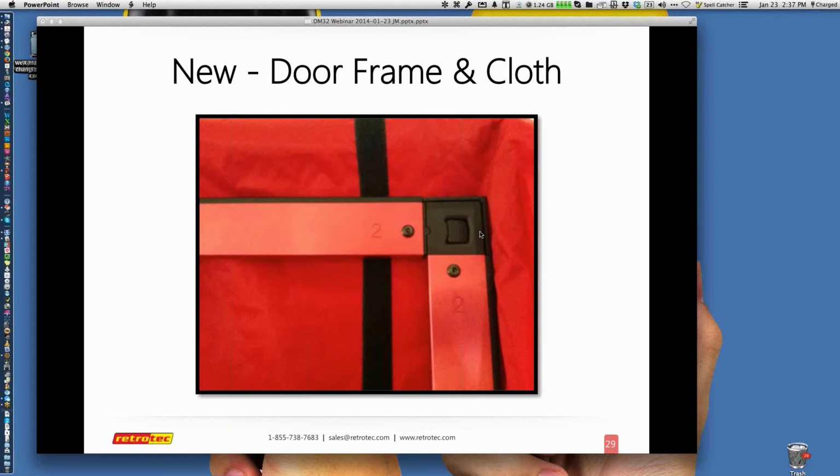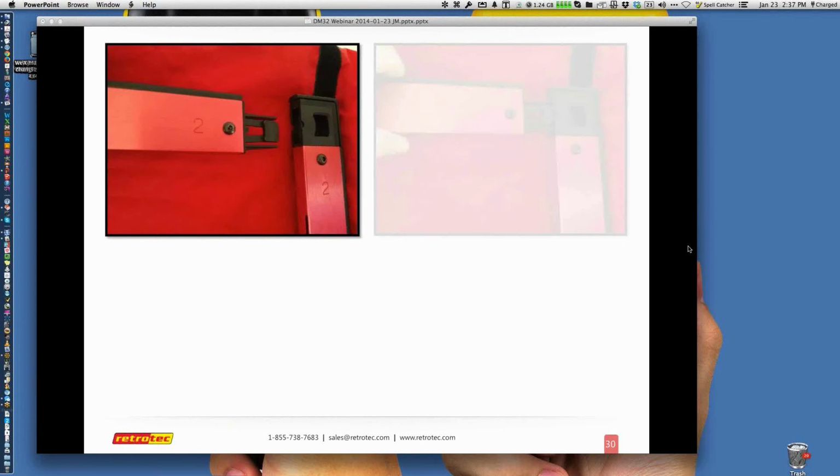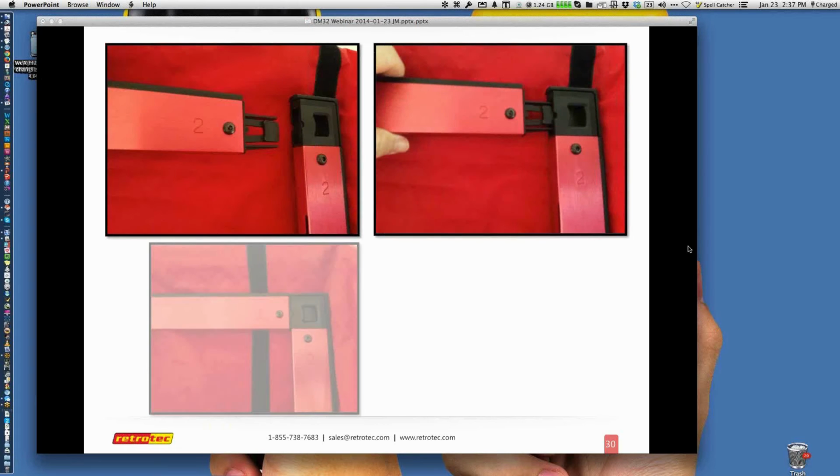So for those people that are doing a Passive House, or so many houses are getting so much tighter now that you want to try and reduce the amount of leakage that's happening in the door cloth and the frame itself. So they really have the weatherization, the weather stripping that goes all across the top. It does a much better job of trying to catch this corner so it fits tighter into the frame itself. So it's similar to something you may have used with camping, on how it comes together with a few fingers and pops in.